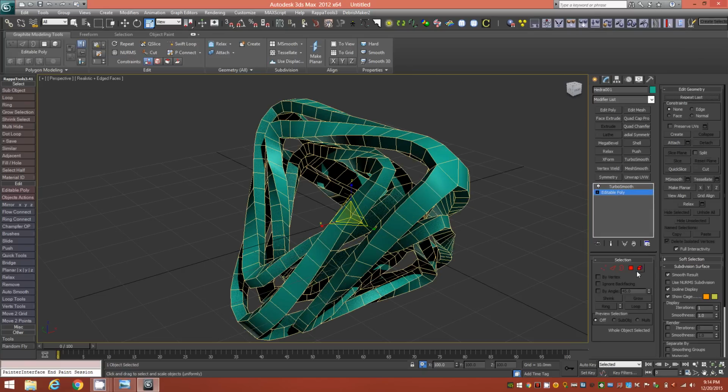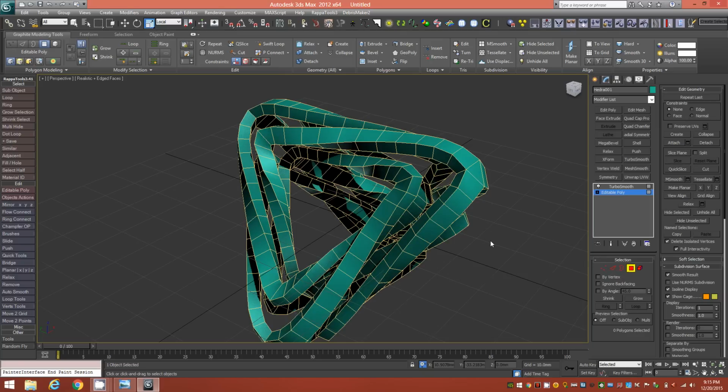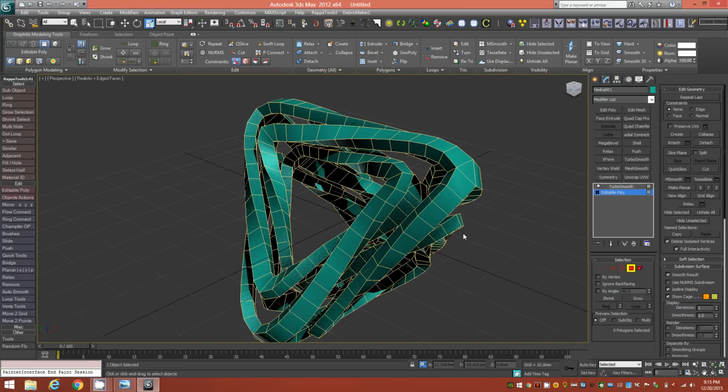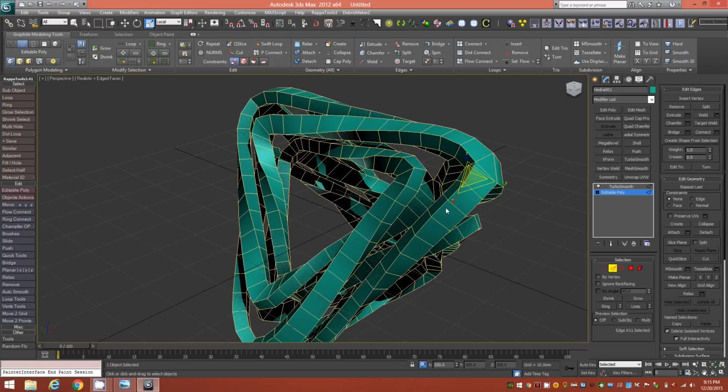The editable poly object has the crease edge feature. Newer versions of Max, you'll have a crease edge modifier, which will work excellently with the new OpenSubdiv. But in this case, I'm using Turbo Smooth, so I'm going to use the old-fashioned crease, which is not as slick, not as good as the new one, but it works nonetheless. Well, it seems I lost all of my internal selections here, so I could just go ahead and select these manually.